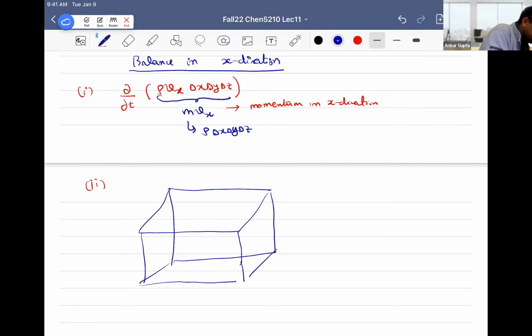So could anybody physically, if you have not seen this before especially, tell me what do you think is momentum outflow or inflow? What does it mean? Momentum outflow, what would it physically mean? Absolutely. So basically physically it means some sort of momentum is leaving the surfaces, right? So we have 6 surfaces, so something leaving the surface is the outflow. So inflow is minus of outflow, right? Inflow and outflow.